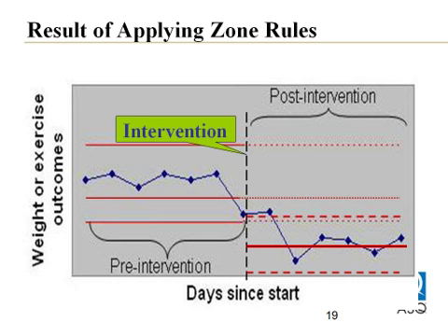And after we did our intervention, which was correcting the support frames that the circuit cards were being held in as they went through the liquid solder, and those were warping because they'd been around for so long and nobody had checked them. Once we replaced all those frames, the boards went through smoothly through the liquid solder, and you can see that the defect rate went way, way, way down. So this is a good way to share information like this with the people you may be responsible to, or to explain why something has happened or why it hasn't happened.